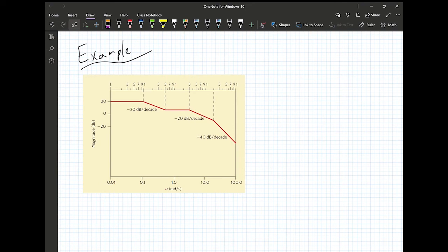It should be clear from the magnitude response what is happening as far as the poles and the zeros, right? The first thing we could notice is that we're starting with 20 dB. So that's our starting point. Typically, if the gain is 1 in the transfer function, so we have some k0, and then I have the zeros, and then the poles, right? If the gain is 1, I will start at 0 dB, because I'm starting at 20.